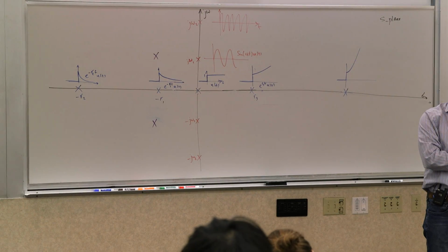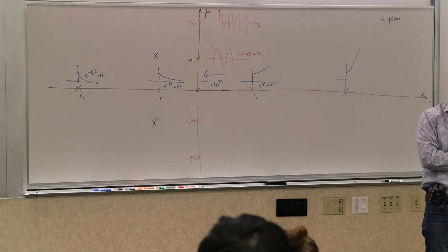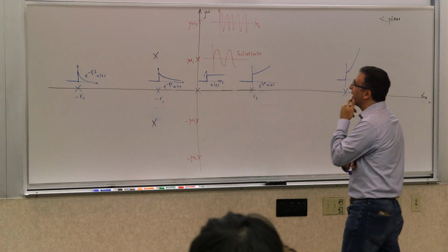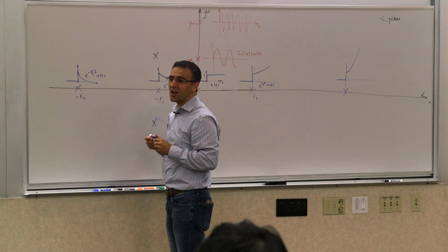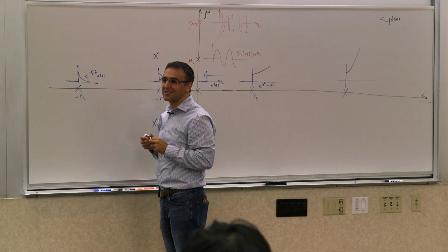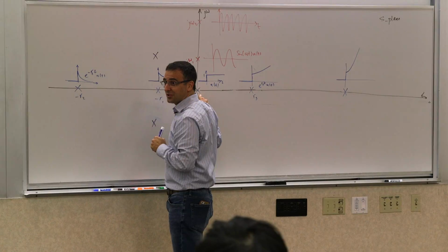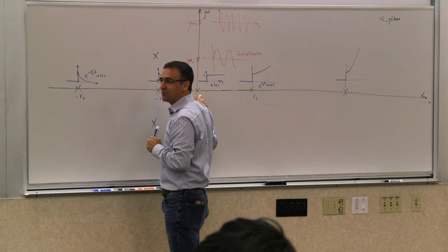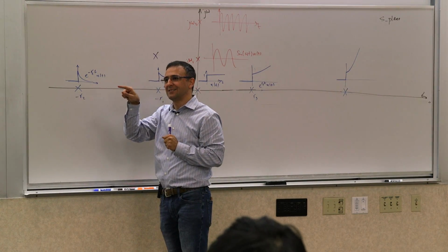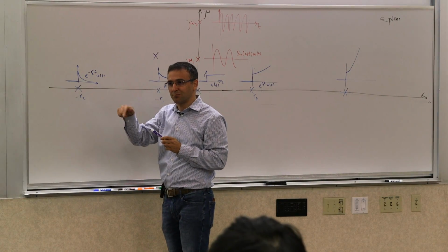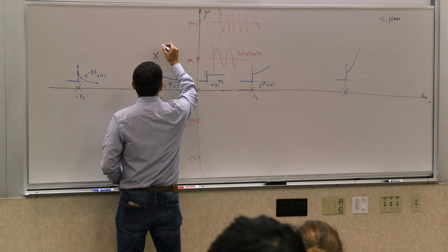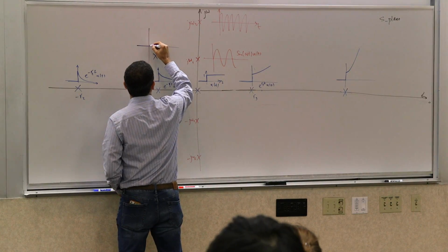And what kind of response do they generate? Decaying sinusoids, right? So if I have just this, it would be a decaying sine or a decaying cosine? Decaying sine. If I had the 0 at the origin also, that would give me a p. Or a 0 somewhere else can give me even p somewhere. So, decaying sinusoids, right?